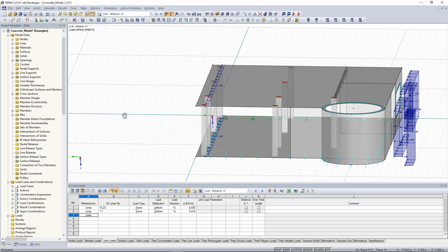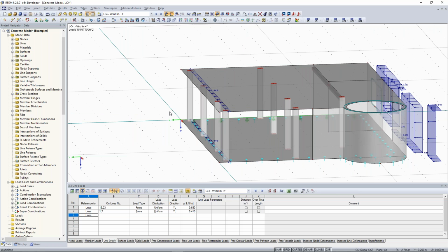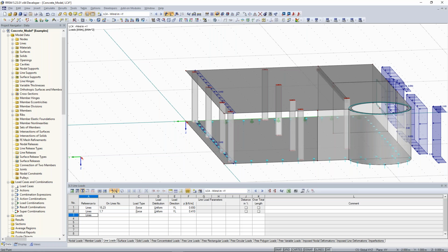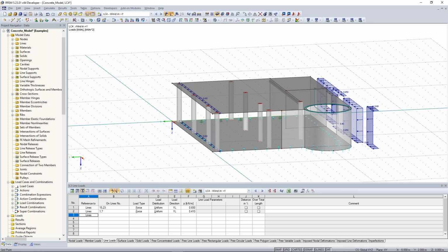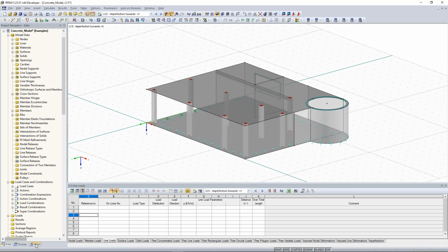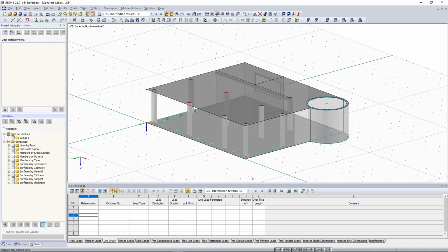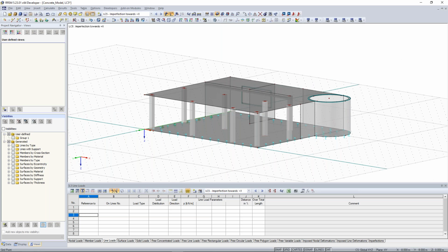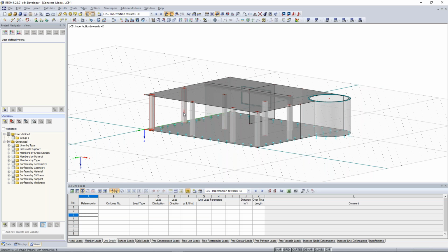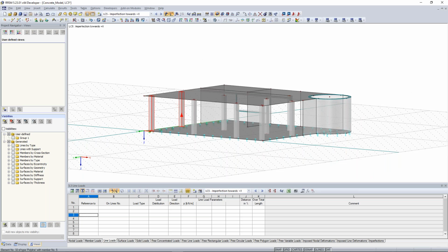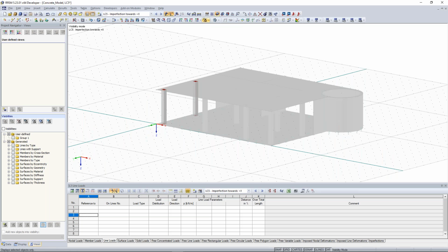Very easy. Good. Now, next thing, the insert of imperfections. So first of all, I refer to my imperfection towards the positive X direction. In order to filter something, I can really recommend you to work with the Views navigator. Click here to the Views navigator, and now you just want to see all columns. Yeah, you can select every column, and then you can say, okay, show me the visibility, show me these objects, show me the visibility by selected objects. Yeah, this is one possibility, but there's an option where you can do it much faster.